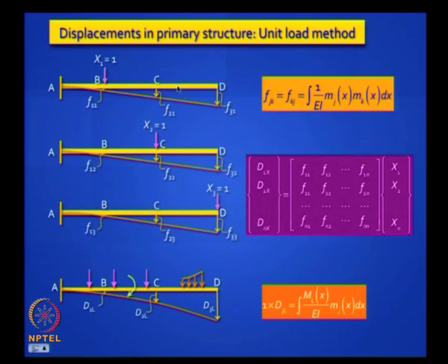So the beauty is whatever unit bending moment diagrams that I drew for this and this and this come in handy when I find these deflections, right, because if I want to find d1l, I need to apply a unit load here, you understand. So this bending moment diagram caused by this is called m1 and so on and so forth. So those moment diagrams come in here. So you need how many diagrams?